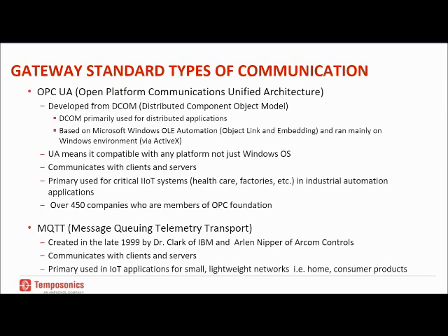So if you develop in a Linux environment, or on something other than Windows, you can still access OPC-UA specific data. Again, that communication happens between the server, which is the gateway itself, and the clients, which is anything out here listening, whether it be a laptop or similar, that's listening for that OPC-UA related data.